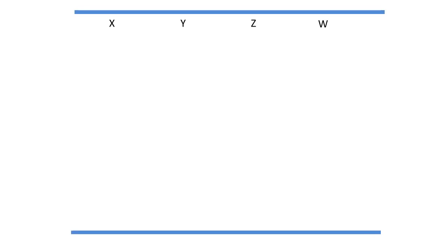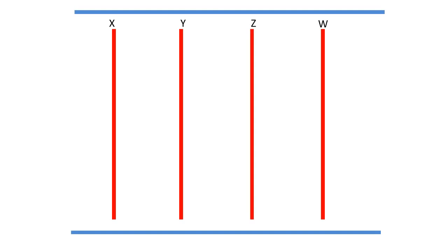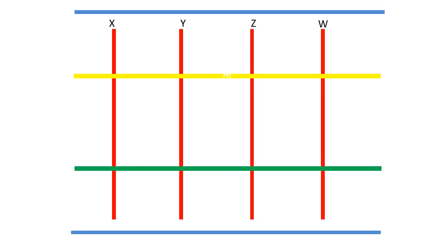First, draw the VDD and the ground connections. Following them will be the x, y, z, w polysilicon layers. Yellow color represents the P substrate in the PMOS section and green color represents the N substrate in the NMOS section. We label the PMOS transistors from drain to source by exactly following the sequence from the Euler's path.